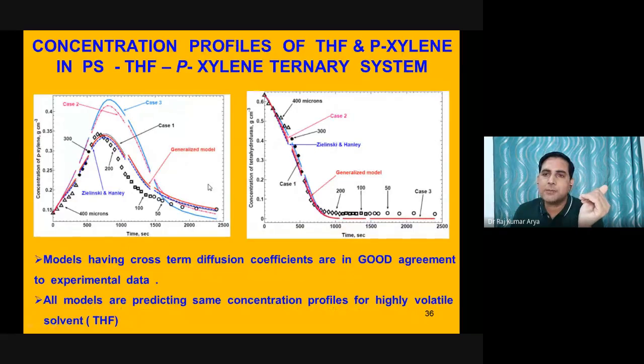Now, once we have done the optimization part, we want to compare our model predictions with drying experiments. So we did the depth profiling. Here we are comparing which model is good, because previously we have seen 4 models, but there are 4 or 5 more, because they have put in some constraints, since some cannot measure the diffusion coefficient or the activity coefficient properly.